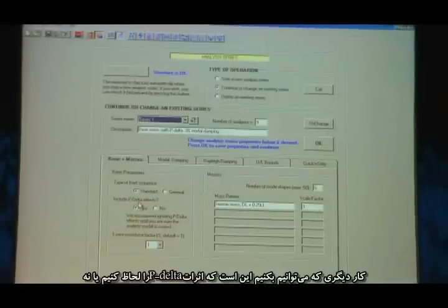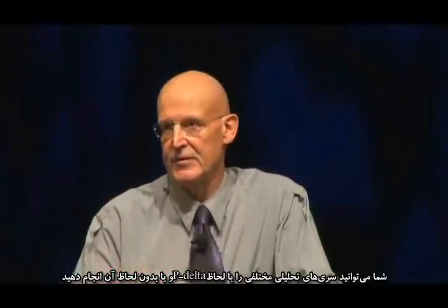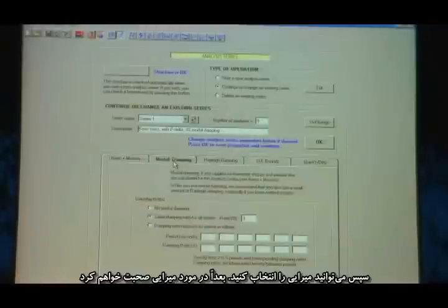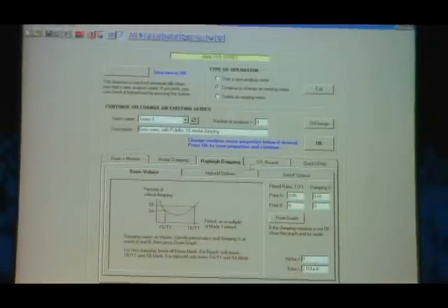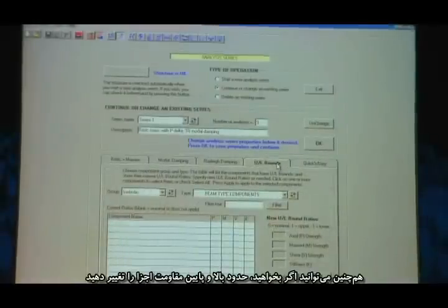The other thing I can do is choose whether or not to use p-delta effects. So you might run one analysis series ignoring p-delta effects, another one including them. And then you can also vary the damping. Later on today I'll talk about damping. You can have modal damping or Rayleigh damping. And there's a bunch of other things you can do. You can even vary the strength of the components using upper and lower bounds if you wish.